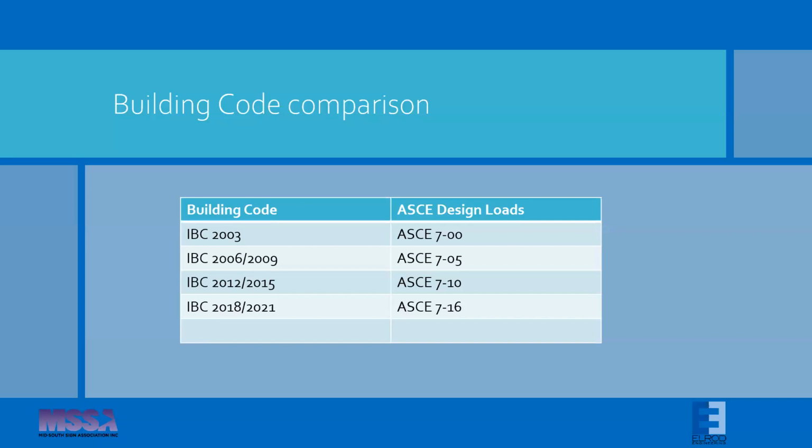I'd like to make the point that just because something has stayed up in the past or has always been built a certain way doesn't necessarily mean it is properly engineered. We'll talk about this a bit more a little later, but wind loading is a good example. Signs typically have to withstand a 115 miles per hour wind. I'd be willing to bet that nobody listening to this webinar has actually experienced 115 miles an hour wind unless you've driven an unshielded motorcycle at almost twice the speed limit. That wind force is what we need to design signage for.